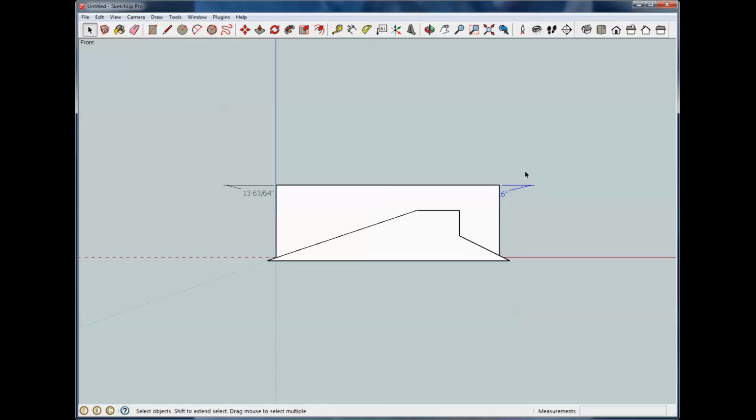I've got drawings that have dozens and dozens of scenes in them, but one of the nice things is in this scene we can go in here, and instead of erasing this, we can hide it. Now there's an option under View to show hidden geometry. You can see it shows up there. I'm going to turn that back off, but we can hide views or hide entities within these scenes. So if you want to cheat and do it that way, you can.